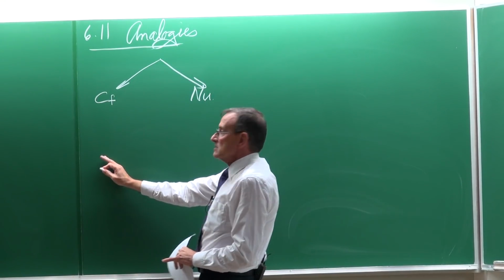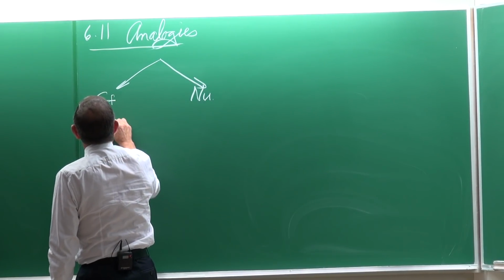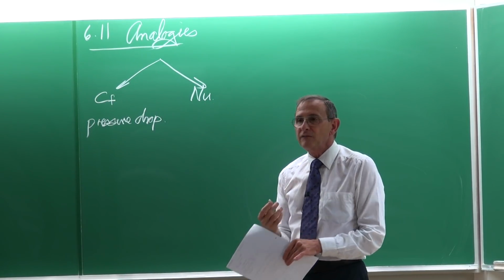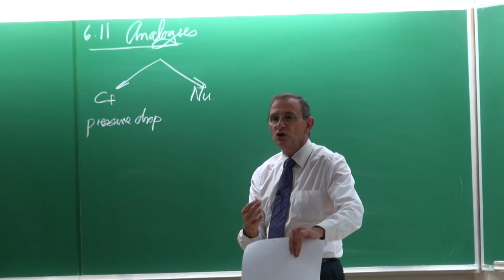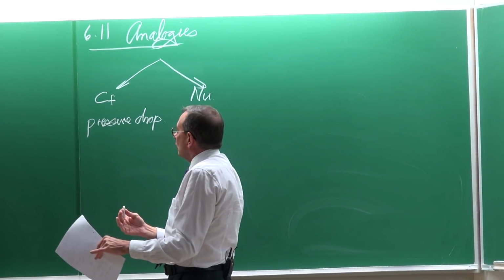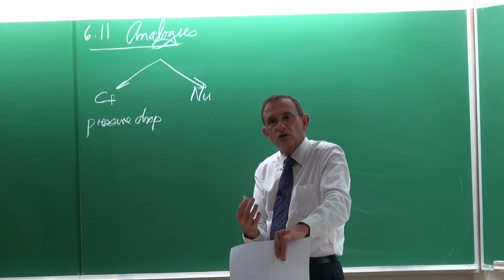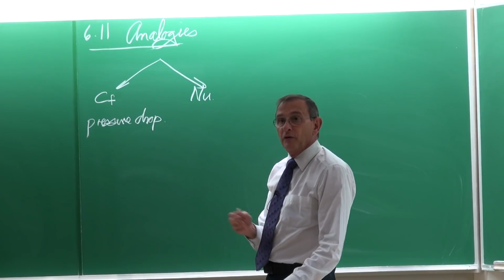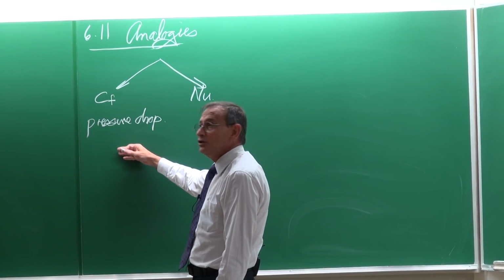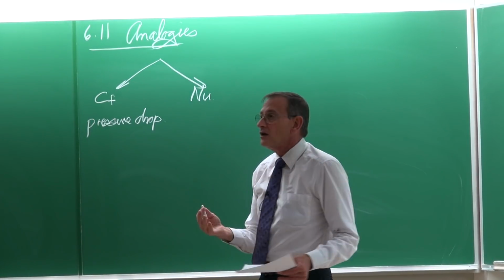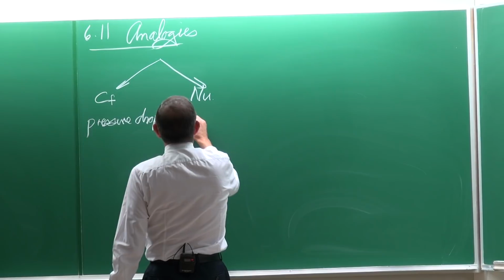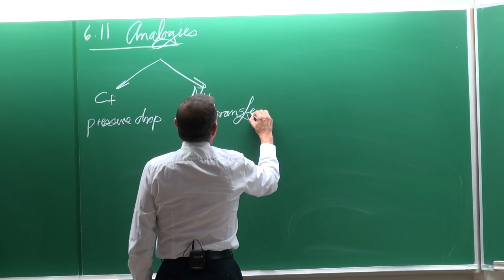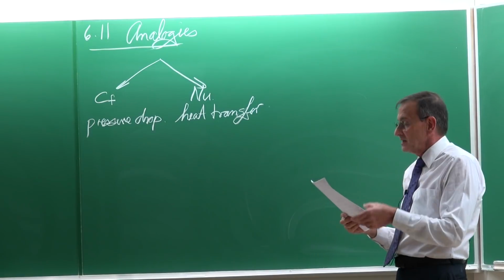The moment we've got this, then we can normally determine the pressure drop. Pressure drop is important to us as engineers because you pay for this pressure drop because of a pump you're going to need, or a fan, or an aircraft engine that needs to propel an aeroplane. So we are always interested in the pressure drop. And of course, there are some cases where the pressure drop will be given to you, where you then need to determine the friction factor or the skin friction coefficient. With the Nusselt number, the moment we've got the Nusselt number, normally we can go and calculate the heat transfer. So that is why it is important.